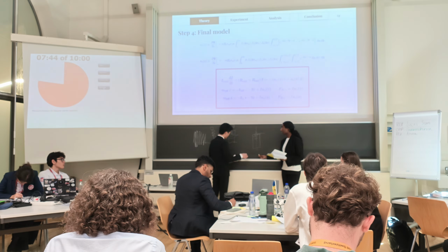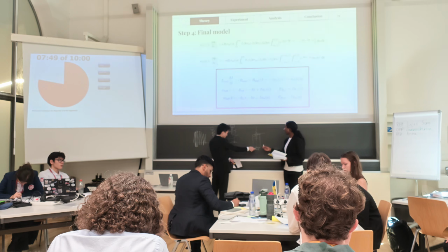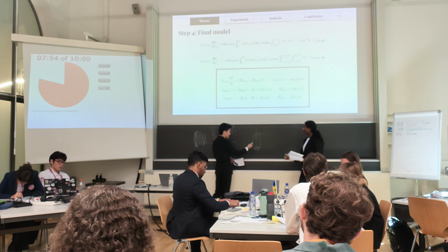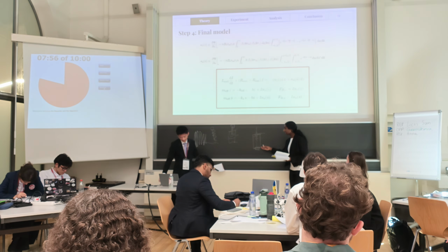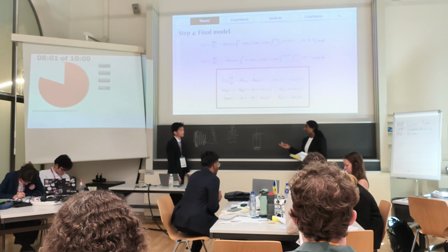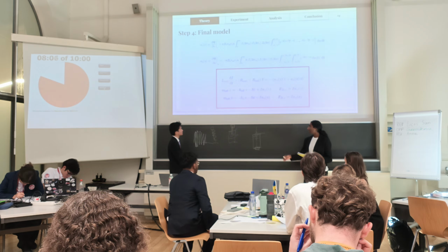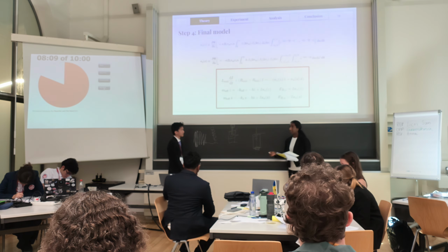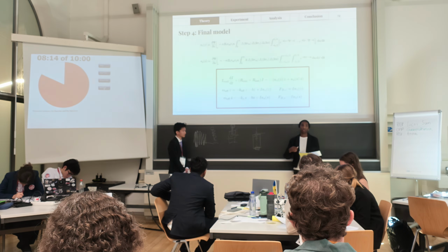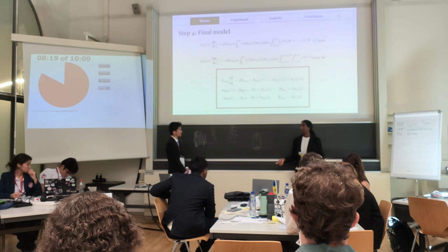Yeah. And one very important regime of the damping is when the damping is maximum, and that actually occurs when the equilibrium position of the magnet occurs at the end of the coil. And so we of course want to show this case, which is really important. I think this is a nice way of showing it. However, I don't think that every parameter variation or every trial should have included this, especially since the problem statement does not state this. However, I see that we have come to a disagreement on whether the magnet should be within the coil or not. I believe that this is an interesting phenomenon to investigate. However, it shouldn't be central, and all the trials shouldn't rely on the magnet oscillating outside of the coil.